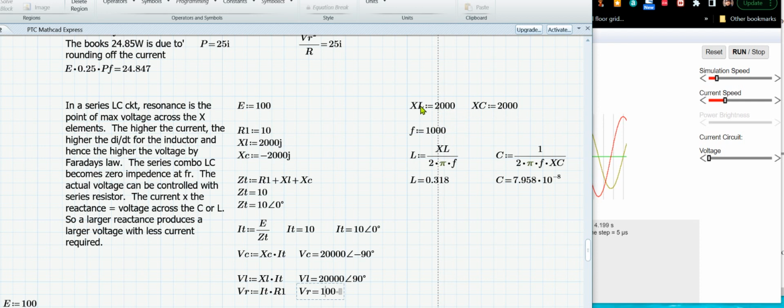But anyway, I just used real values instead, to make sure there's nothing weird going on. Here's the capacitive value for a given frequency. It's at 1 kilohertz, and with this reactance that gives us about 79 nanofarads for the capacitance and about 318 millihenries for the inductance.